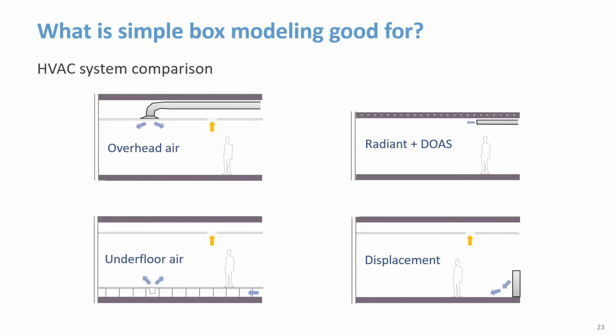And underfloor air distribution and displacement ventilation work best with higher ceilings and may also affect the floor-to-floor height. It's important to keep in mind that an HVAC comparison does require careful attention to model inputs so that the comparison turns out to be realistic. So it's important that somebody knowledgeable with these systems should be involved in that kind of analysis.